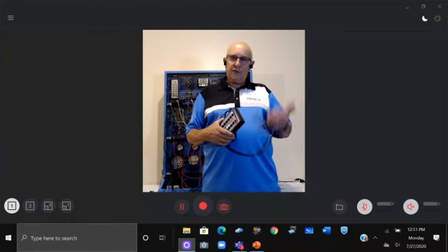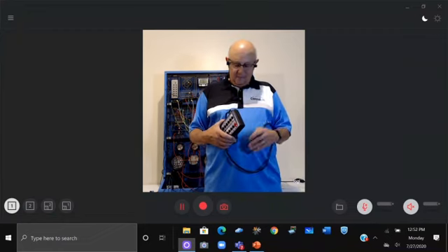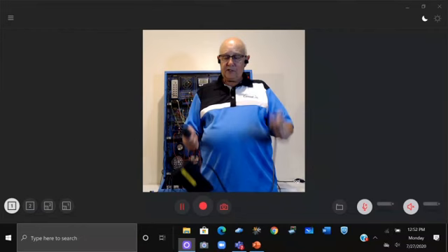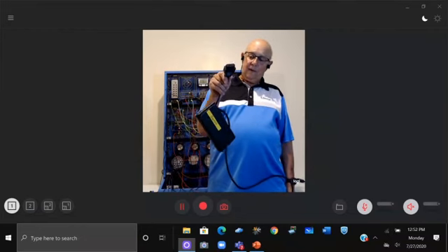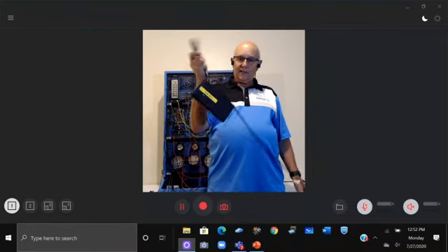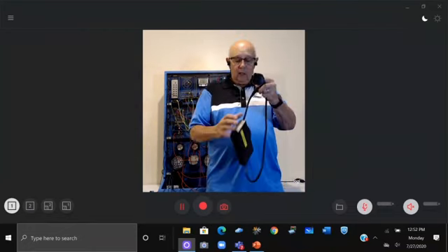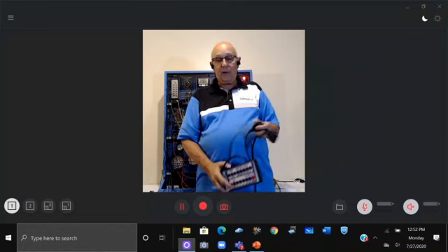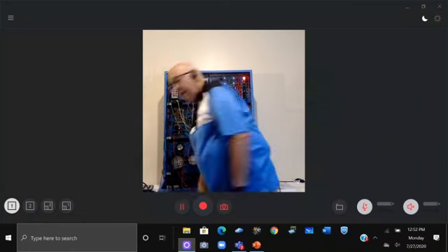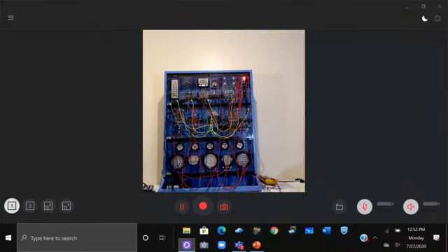Do not let students plug anything directly into the DLC, except maybe a scanner. This one goes into the DLC. Here's a connection for a scanner. And then we have a switch on the top that we turn off, and that lets the scanner just feed through without worrying about the lights or anything else. So we'll show you that in a little while. Okay, I'm going to switch back over to the PowerPoint.